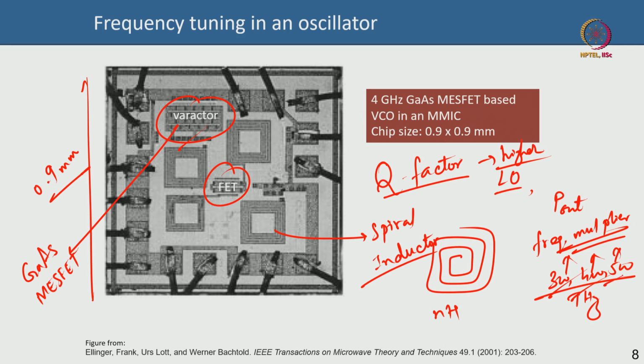So, the Q factor, the conversion efficiency, the power output that you are getting at different frequencies like 3 omega, 4 omega, all of these are figures of merit, and in something like an oscillator there are even things like phase noise, which is also a figure of merit. So, there are many things actually that are involved in all these RF components and chips. We cannot cover everything in a course, we are only trying to understand the varactor and frequency multiplier here in the context of a real chip that is being developed. The next thing that we will have to talk about is actually to understand the working of a varactor.